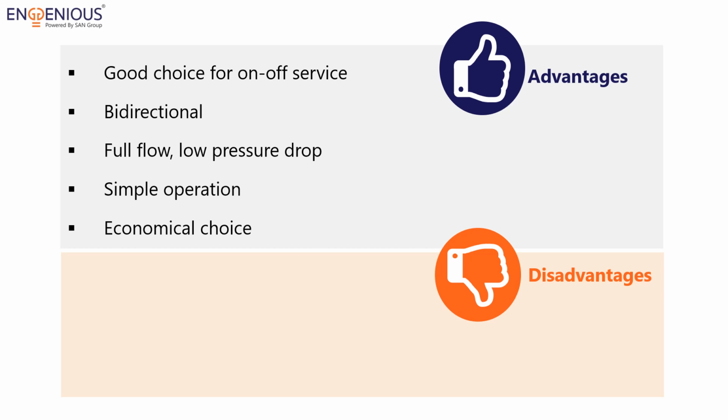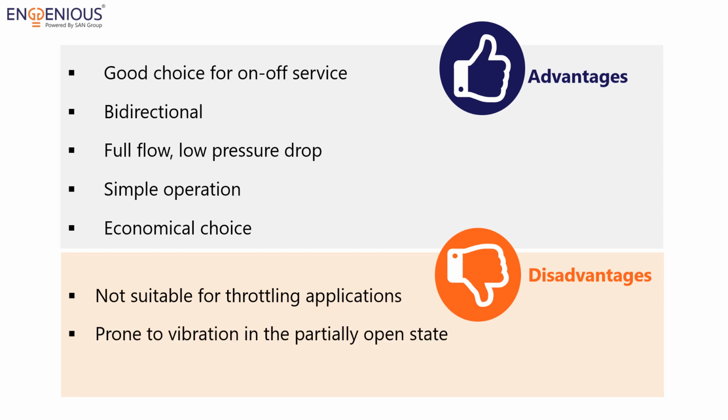Disadvantages of using a gate valve. It is not suitable for throttling applications. Gate valves are prone to vibration in the partially open state. It is subjected to seat and gate wear.